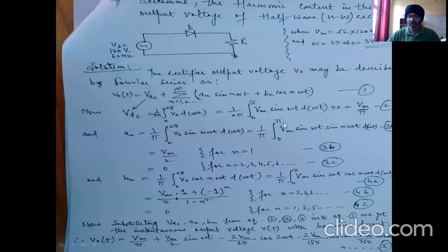And then we can calculate these values if we know the frequency, just by substituting the frequency in this. And if we know the peak value, substituting it over there, we can sum all these things up, and we can calculate the individual harmonic content as well as the total harmonic content. If we sum all of them up, we find the total harmonic distortion. And if we find it individually, we can easily see which harmonic content is actually causing problems, and it should definitely be removed.